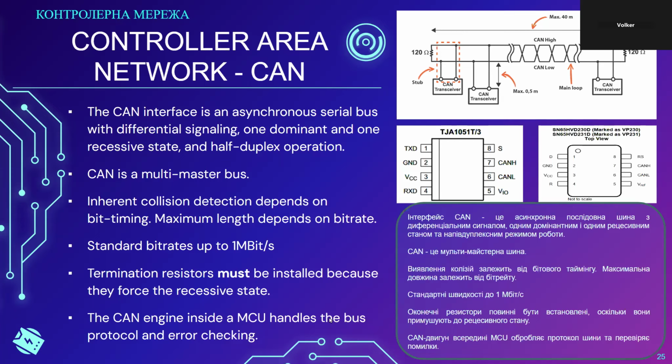So, for example, you have a brake that is malfunctioning, and the brake controller has to tell the main engine control unit that a brake is malfunctioning. So that message will get the highest priority, the highest message ID, which actually is the lowest message ID, but that's just because 0 is the dominant state. So it is meant for that kind of environment where there are short messages of high priority that have to be sent very, very quickly.